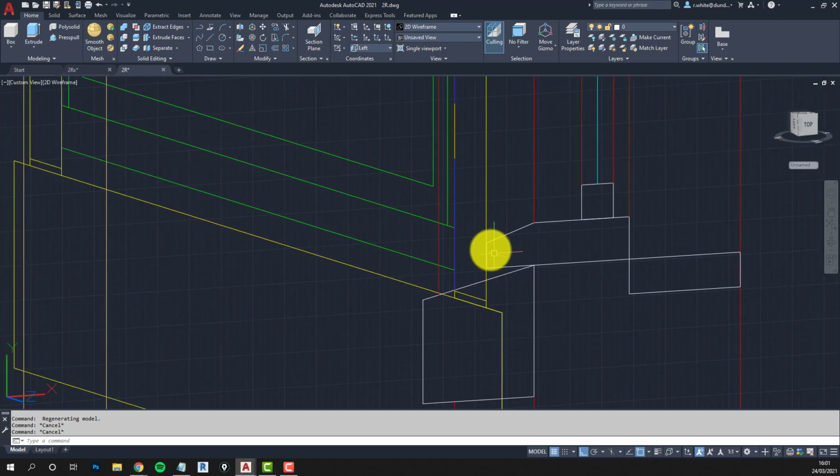Okay, always test things with your 3D. Use distance to check what's happening. And you're looking for this, in this case I'll be looking for differences in the Y coordinate. So is this point higher than that? Is this point higher than this? Etc. Okay, so it's distance. Okay, the Y direction should be 0. Distance again from here to here. Y is 0. Okay, we're all looking good here.